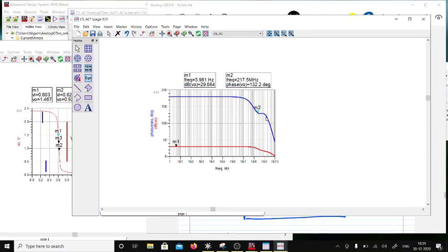And before that, this has become plus 90 here, which means that there is a 0 which came in to correct. So there was a fall off at 20 dB per decade, and as soon as you get a 0, you will be at 40 dB per decade, and then there will be another corner coming here. So it will give you an additional 90. So 90 roll off, flat, or plus 90, right? And then another roll off. Now what I want to check is where the gain becomes 0 here, and what is the phase?